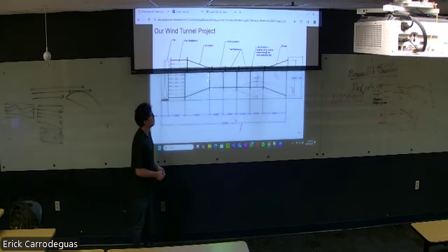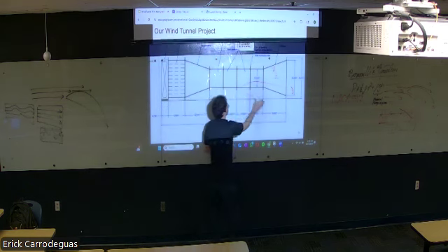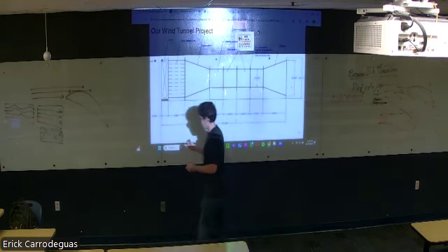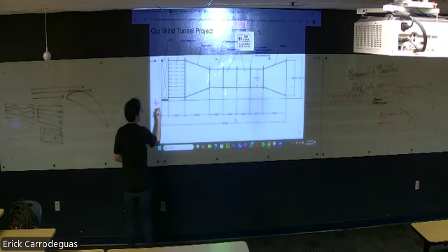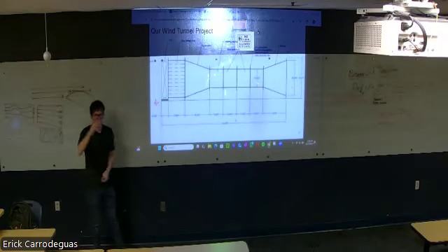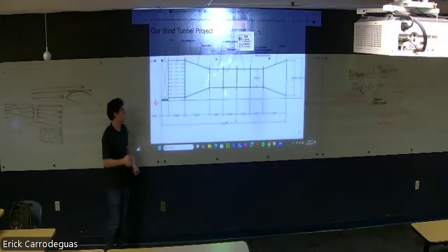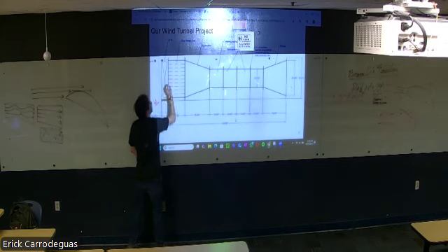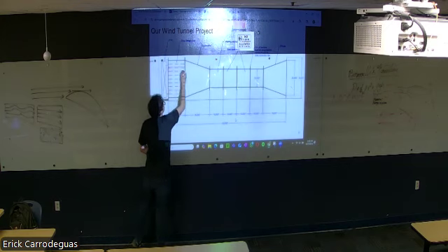So in a wind tunnel, it starts from here and ends all the way over there. You have a big fan which is causing turbulent flow, right? So in order to correct that, we have these flow straighteners. Right now we're going to use snap tubes for these. As you have turbulent flow going inward, the flow straighteners correct the flow going into the wind tunnel.